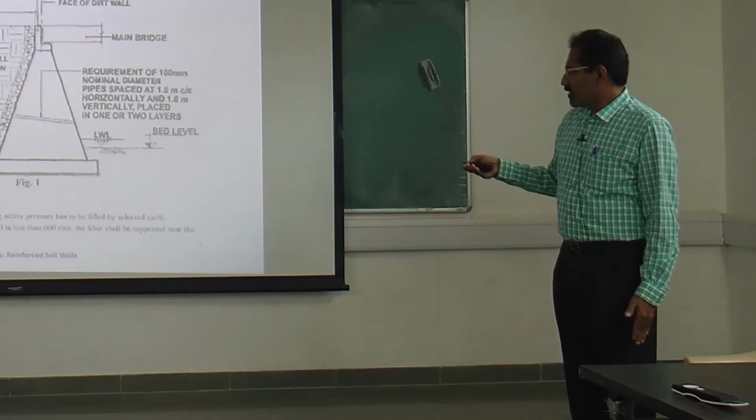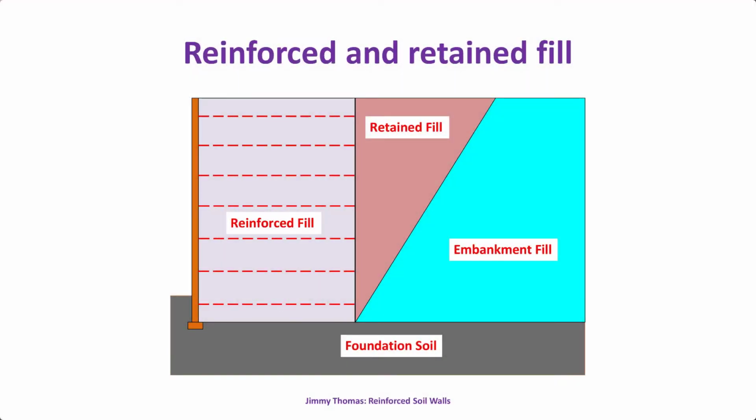don't develop. The same concept we have here, like this is the reinforced soil structure. This part only determines how much tension comes onto the reinforcement. So we need the best quality material in this zone. So we call it reinforced fill.